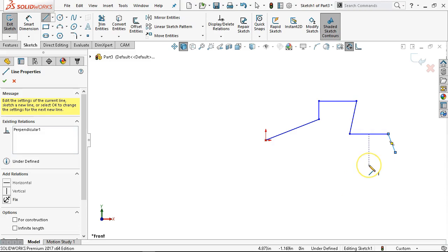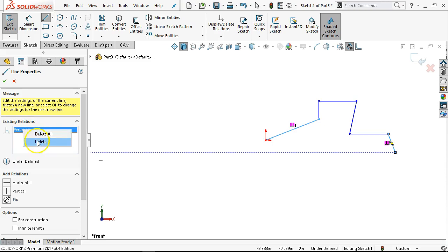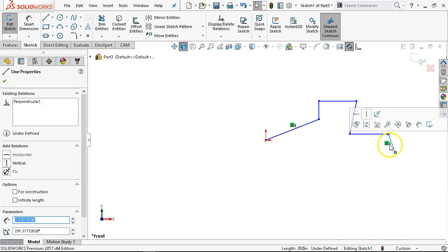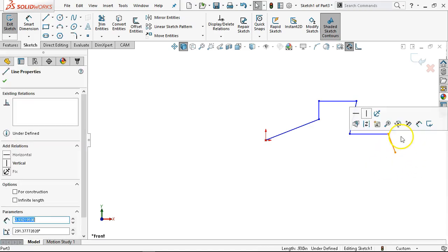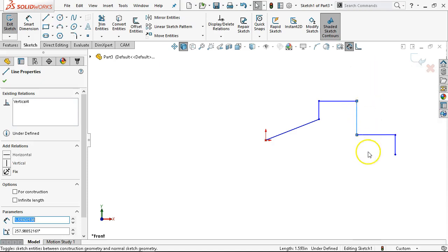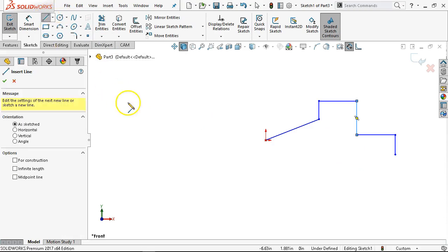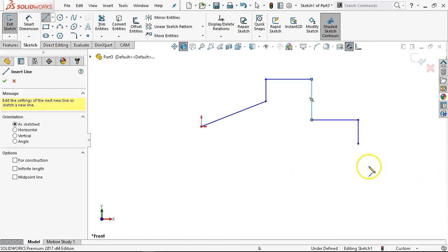All right, if I don't want that perpendicular, I'm now going to have to go back and remove it. Unfortunately, when I discover that it is interfering with going fully defined or I can't put that last dimension in, that's usually the time it shows up. So to get rid of it, let me escape out of my selection. I can highlight the box in the work area and hit delete on the box. Now that one can go to vertical, and that one can go back to vertical as well. So if I recognize it, I'm going to clean up as I go.